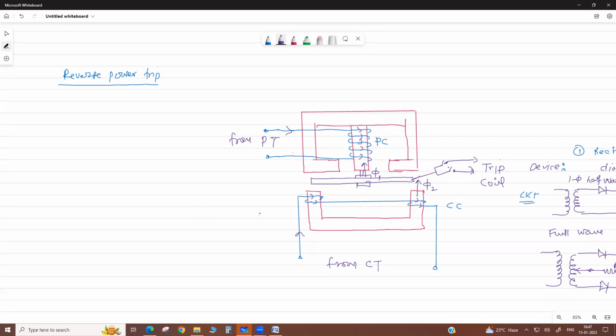Now actually, in a single phase motor, how is the torque developed in the rotor? Due to the starting and running winding, there are two magnetic fluxes in a single phase motor, correct? There are two fields, due to the main winding and the auxiliary winding. So same here, there are two fluxes, phi 1 and phi 2.